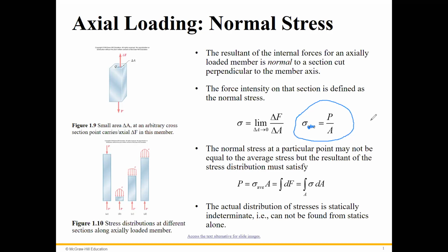If we find the stress for one member, with some certain cross section, and we find the forces from the statics, and we check with the appendix or the allowable stress, and it's greater than that one, which means maybe the system is unsafe, right? Because it's critical, it's greater than the allowable stress. So what should we do to make the safe condition? What do you think?